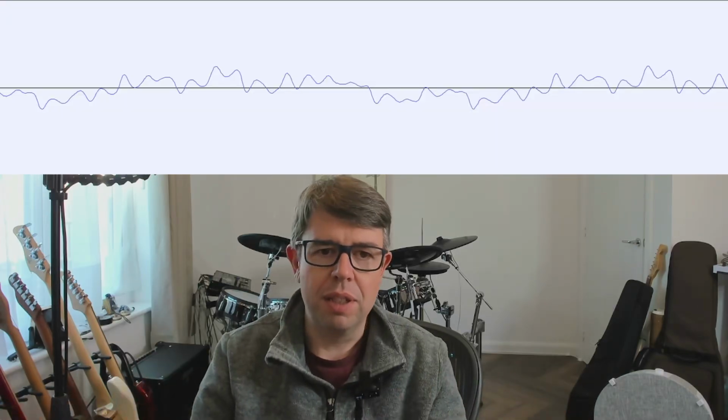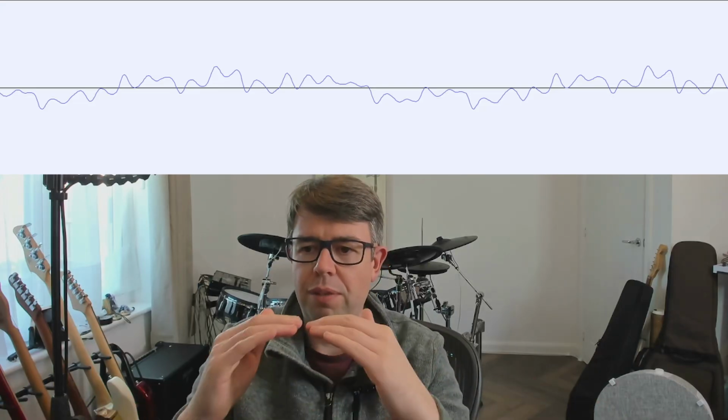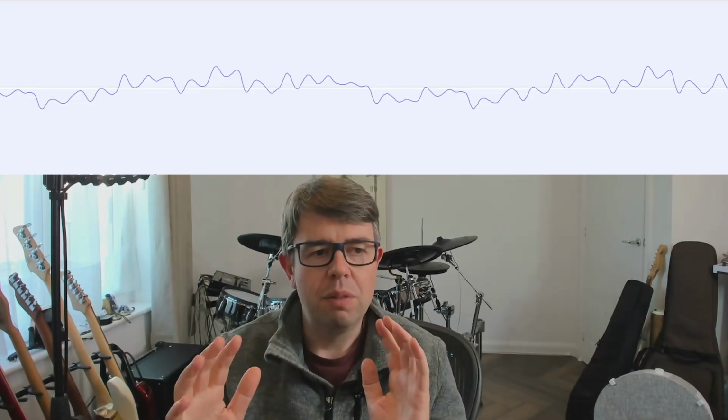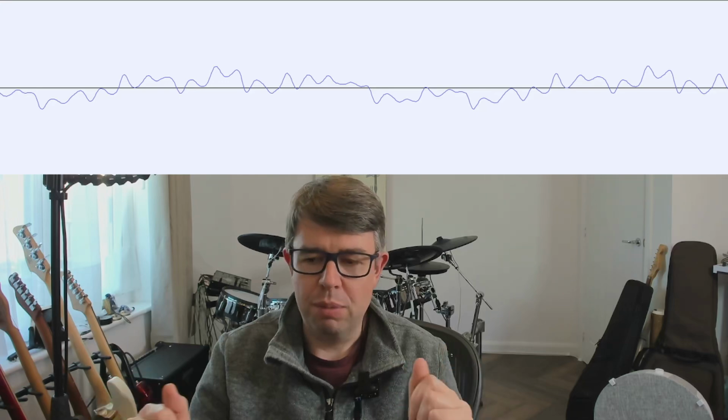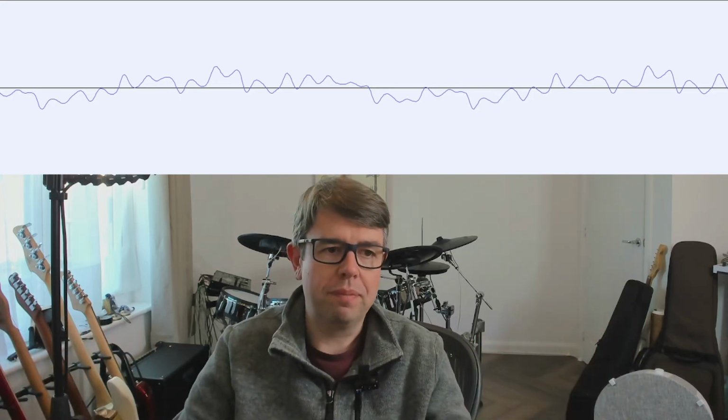Anyway, when I listen to it, the distortion from the QC sounds a bit like digital clipping. So I don't think that's what's happening, but it's pretty easy to go and look and just be certain. So let's do that. As you can see, when I zoom in on the waveform and look at the high points, there's not a flat top there, which is what you would get if it was digitally clipped. So we can conclude that that's not what's happening.